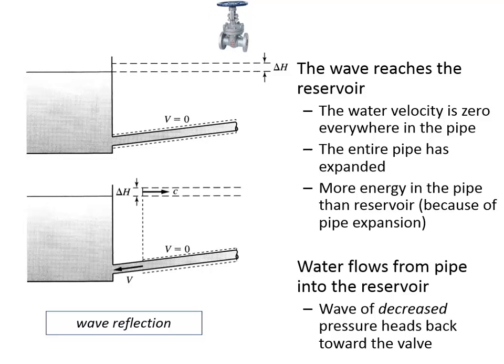And so this wave reflection at a speed that's just incredibly fast is what causes the banging that we heard in the first video. It's the sound of the shock wave going back and forth between the valve and the reservoir. And so in most people's homes, the reservoir, in this analogy, is their water heater.